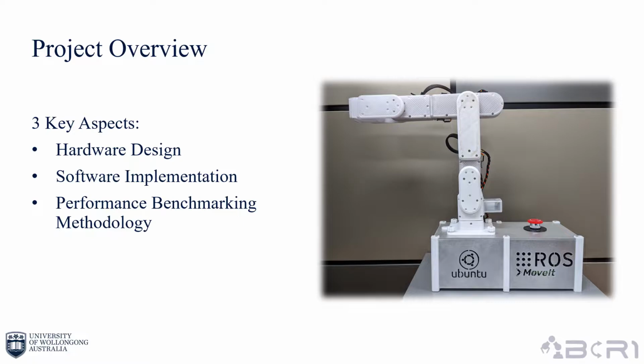The main software that was used is ROS, with the custom control packages being written in Python and C++ with a custom ROS launch file. The testing and benchmarking was conducted by planning paths using the MoveIt Commander Python interface and measuring the readings of the end effector position by probing a dial indicator.